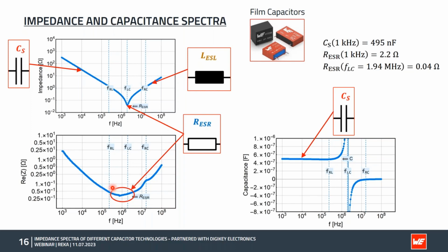Most trustworthy are the results around the characteristic frequency FRC. Towards higher and lower frequencies, it will be difficult for the impedance spectrometer to separate the imaginary from the real part. This usually leads to some kind of U-shaped spectrum with a local minimum around the characteristic LC frequency. The capacitance spectrum does not have a shoulder anymore. It will show this asymptotic behavior. This is actually a physically correct behavior, not just some artifact.